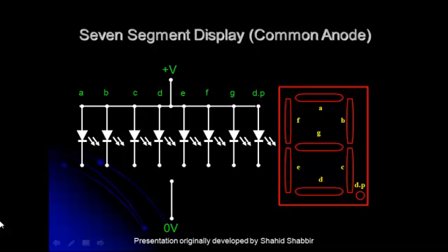So they've already got a plus voltage on the anodes, but the cathodes are the ones that we're going to connect. Now, connecting 0 volts to any one of the LEDs will make a complete closed loop, so the current's got a path to go from a high potential to a low potential, and as it flows through the LED, because of the material it's composed of, it illuminates and you've got the light emitting out of it. Okay, now for this one we need 0 volts, for the previous one, for common cathode, we need plus voltage, whatever that is.